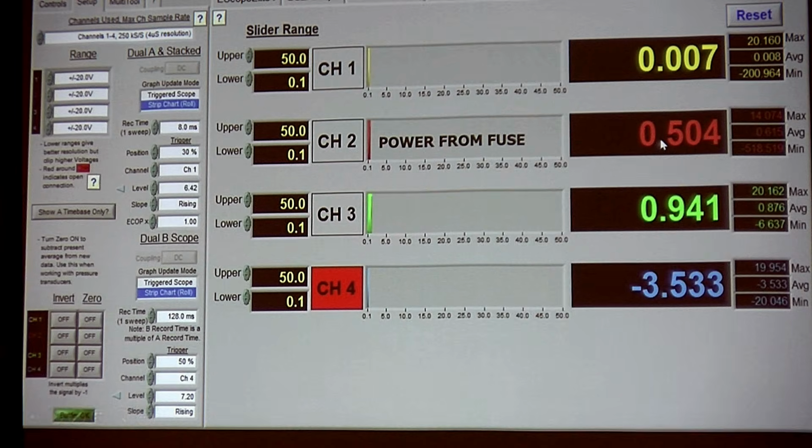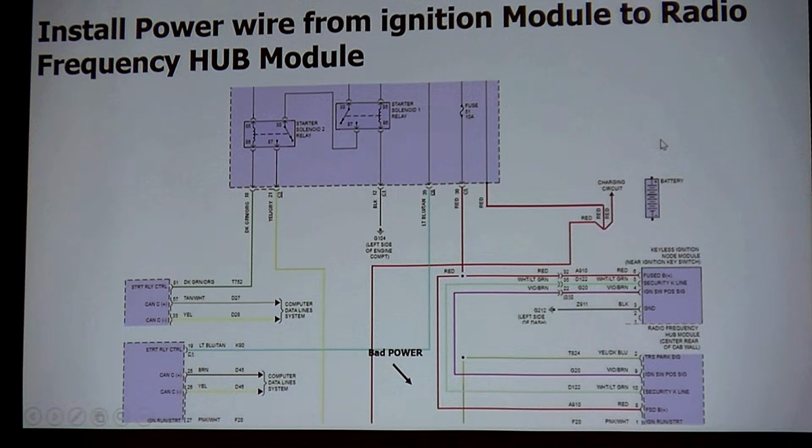That's my problem. So I'm going to look at the wiring diagram, and I'm going to be able to see that this guy sends power down from this fuse right here, and it splits right here. Now, I don't want to go find all that. I know that that fuse is good because don't I have power on the ignition switch? Wasn't I just in that ignition switch? So if I was just in that ignition switch, I'm already back probed, aren't I? Can't I just take a jumper wire from there to there? External? God, we overcomplicate it, guys. Just make it simple. Just bridge it.